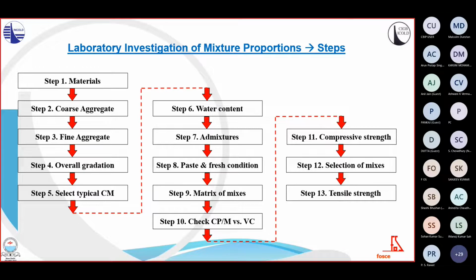And finally, Step 14: conduct other laboratory testing for other specific mix properties as required by the dam designer that up to this stage could have been estimated from published data or experience. These tests may include adiabatic temperature rise, coefficient of thermal expansion, specific heat, diffusivity, modulus of elasticity, Poisson ratio, creep, strain capacity, shear strength, air content, and so on.